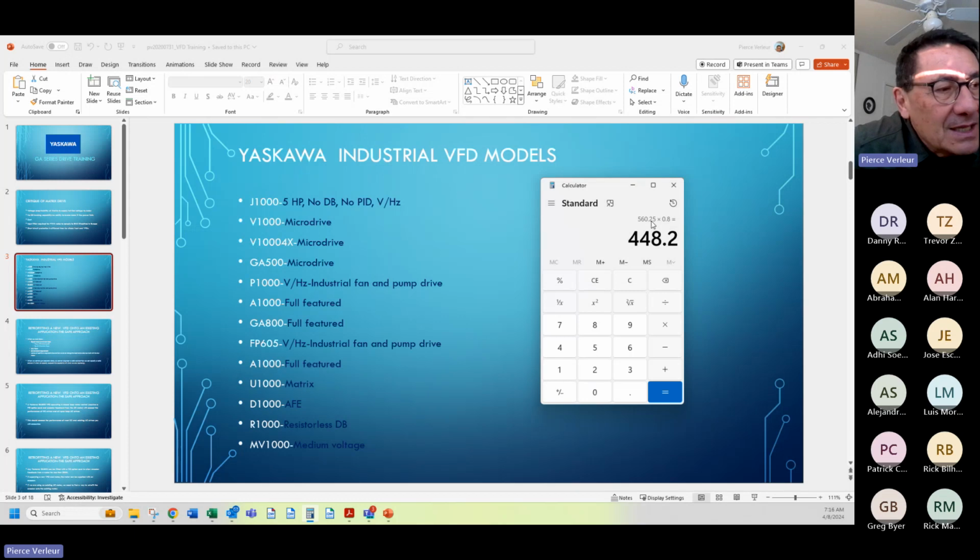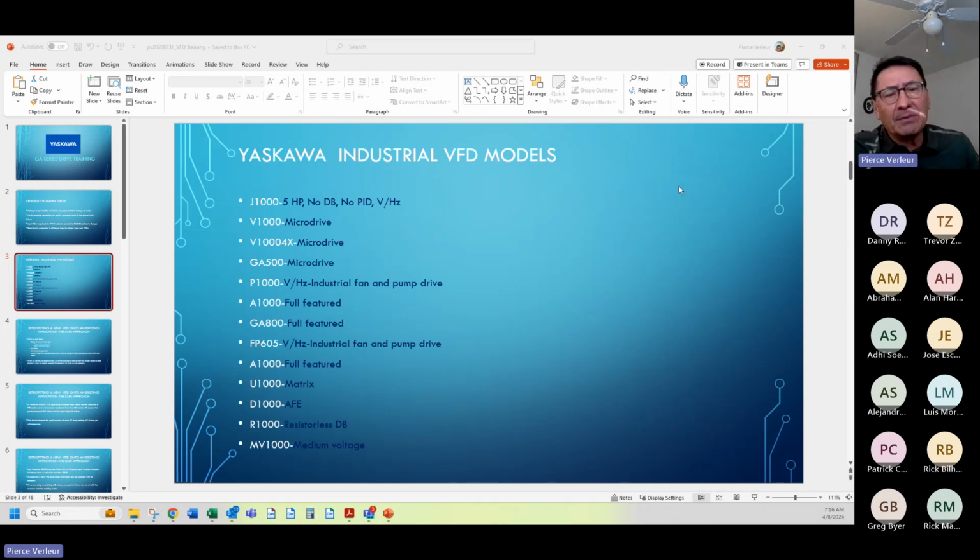So now you understand at this level of power, that's workable, that's reliable, and the NEMA 4X V1000 was quite reliable. You have some other problems with that design, like how do you bring the keypad out? Well, we made a NEMA 4X keypad, and it had a nice waterproof front on it. And then everybody started poking it with pens, as they do to make the keypad work, and they would puncture this membrane, and then water would leak in.